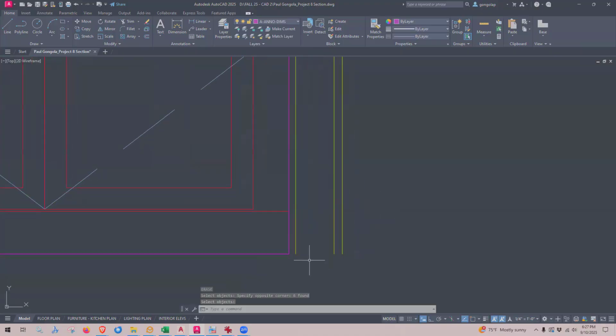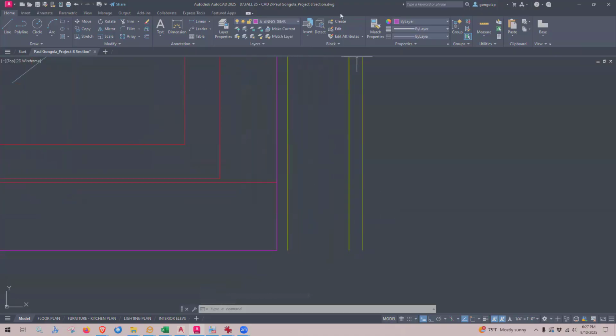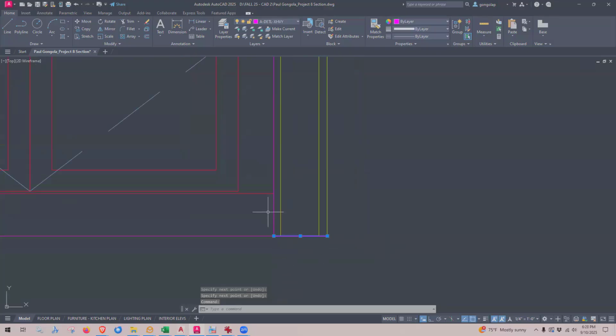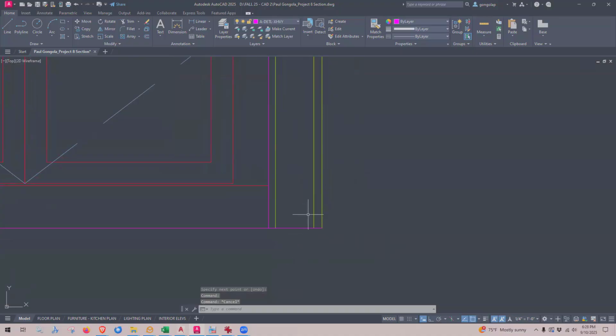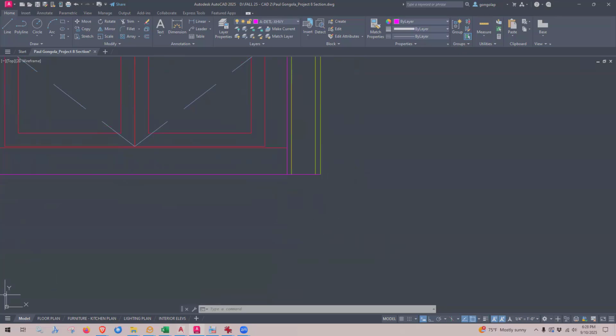All right, so let's do a couple things. First, let me go on to my extra heavy line weight here. I'm making that my current layer. And I'm going to just draw a little piece of floor here. Let me put my snaps back on. That is going straight across like that. That's going to be the top of our foundation wall. That little piece of line right there. And right now, while I'm here, well, you know what? Before I do the studs, let's do the foundation wall.